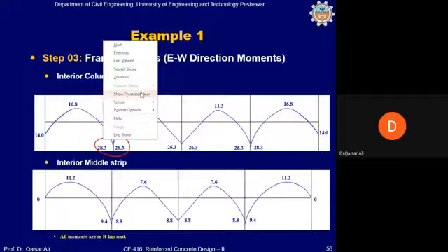Okay, so look at this, pay attention to this, please. The bending moment, which is basically Mu, because this is the factored bending moment, is 28.3 foot kip. We'll convert this into inch kip first of all. 28.3 times 12 is 339.6, let's say 340 inch kip. We will calculate the area of steel for this.